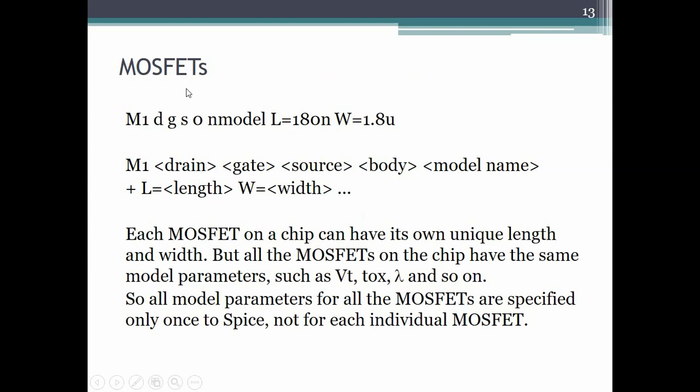MOSFETs. So as I said, there are 4 terminals. So one specifies the 4 terminals. Then one puts what is called a model name, and then the length and the width. So this is the format. Now let me talk a little about MOSFETs.